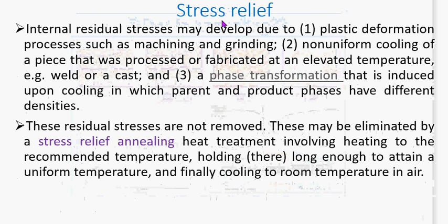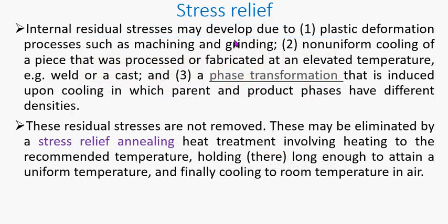So what is stress relief? We've been talking about removing stresses, relieving stresses. Why? Internal stresses may develop. How does it come about? It comes about as a result of plastic deformation, such as machining operations, such as turning, cutting, drilling, or grinding operations. So this can cause plastic deformation in the material, and there could be what we call leftover stresses or residual stresses